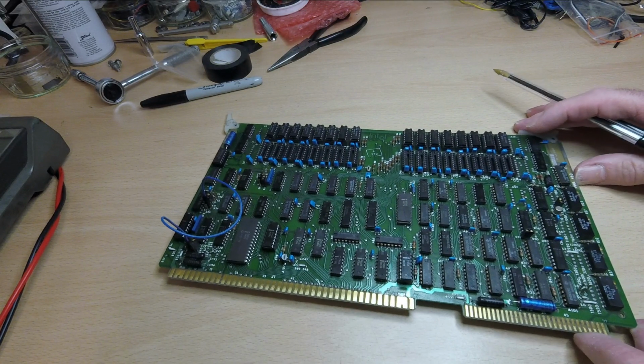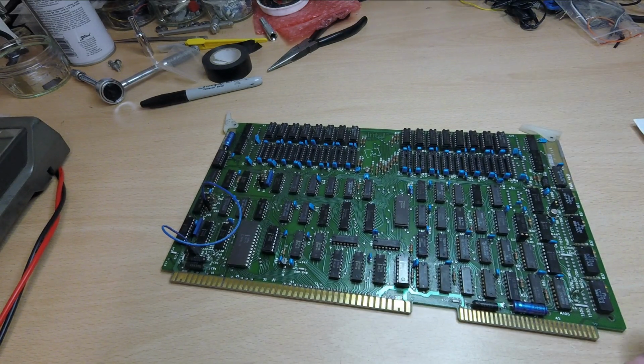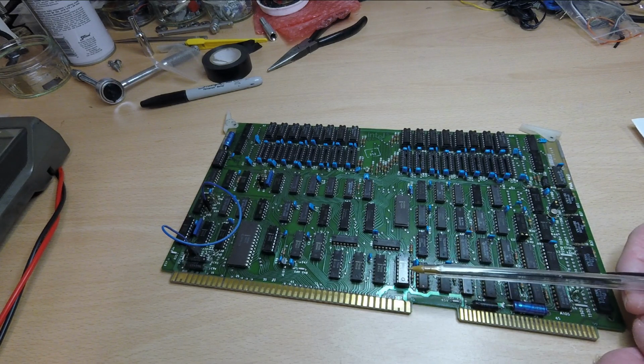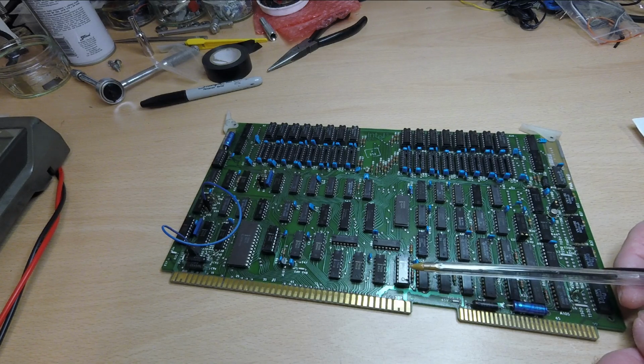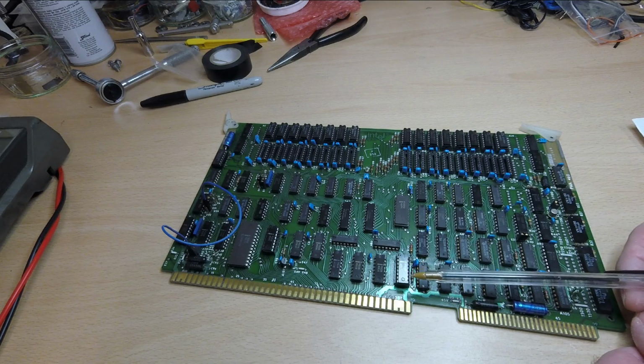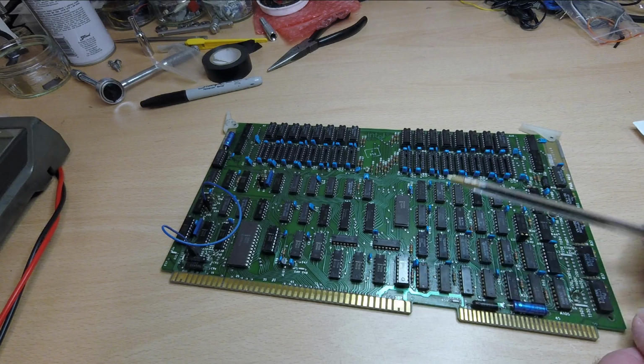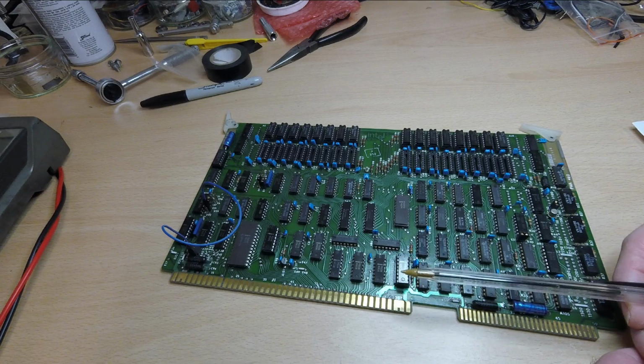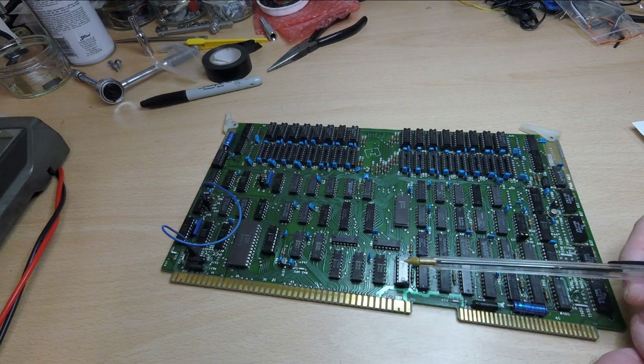I look at the logic analyzer traces again, and it's fairly clear that every time this buffer chip selected, it was actually clamping the lower 4 bits of the data bus to 0. And obviously we were reading that back as F because of the inversion on the data bus. So that's that one. It has cured the problem. I'll elucidate a bit more on that in a minute.